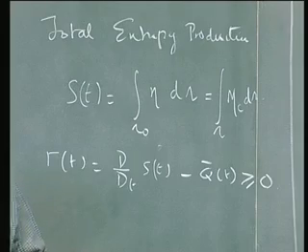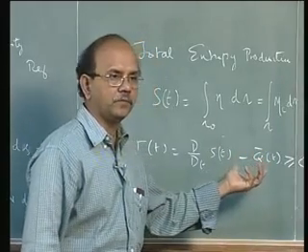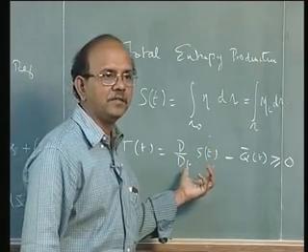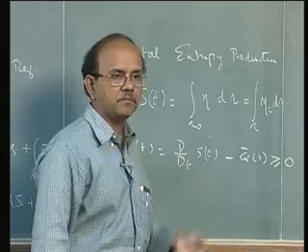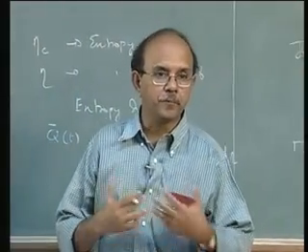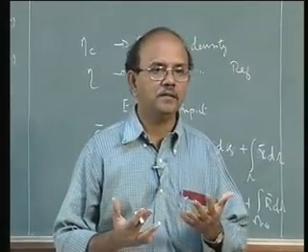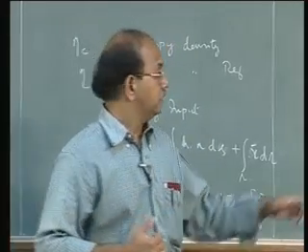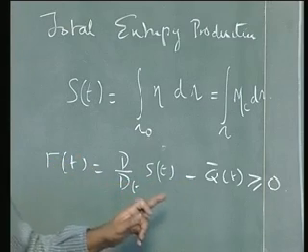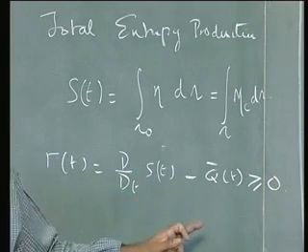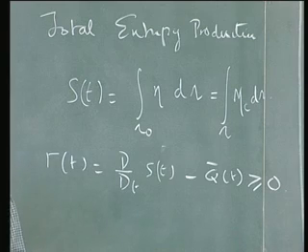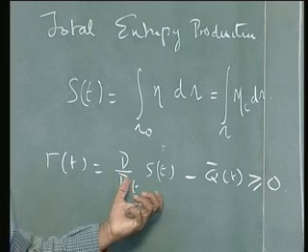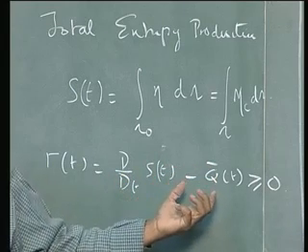The previous equation said that whatever you have given as an input was there to raise the levels of the internal variables. In other words, the previous equation was only a balance equation, balance of energy. The entropy production is not a balance equation. There is an inequality there. In other words, the entropy production is more than what has been given to it.